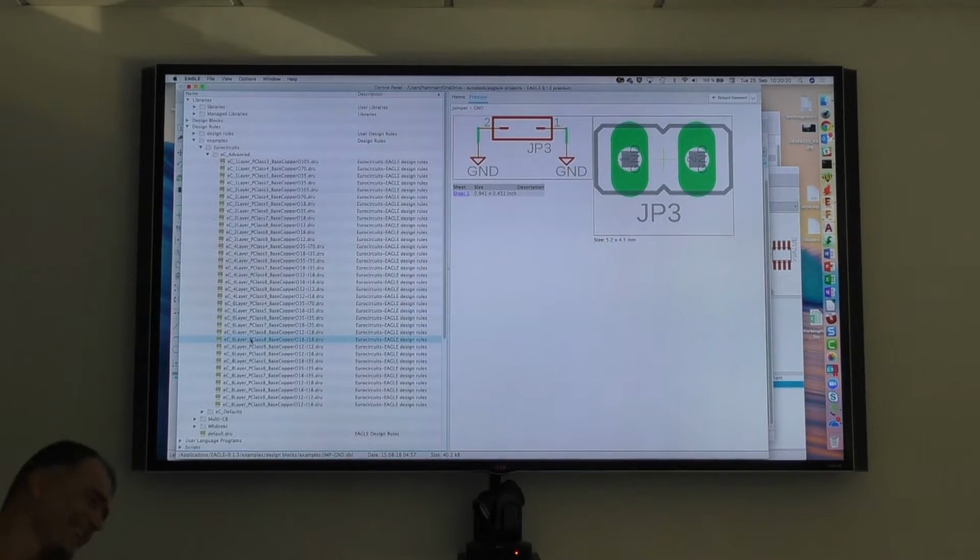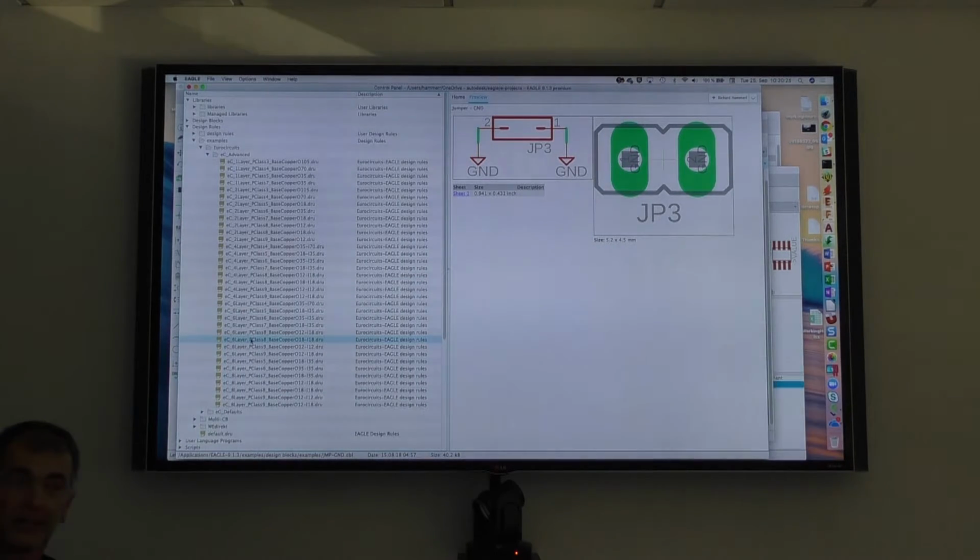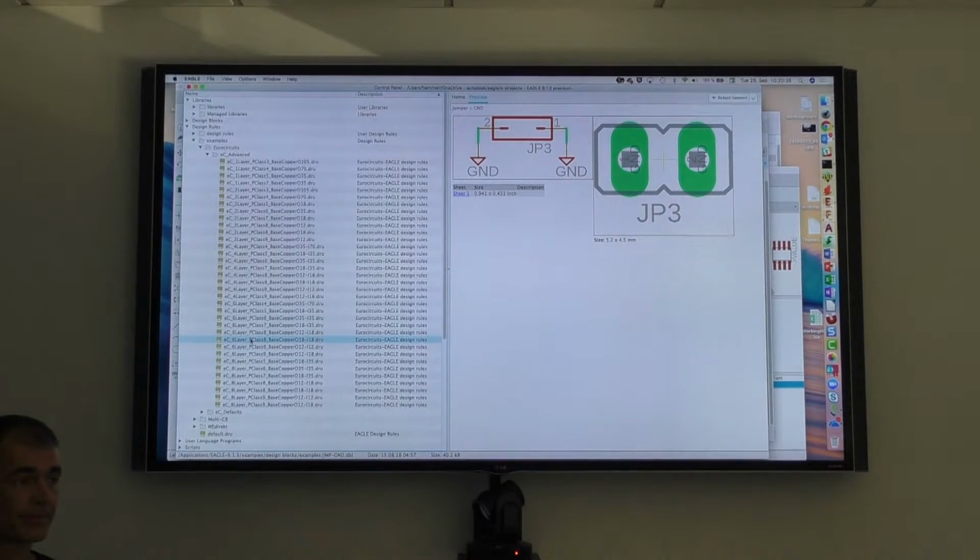Yeah, design rule errors. If you have some, and you send your board or the manufacturing data to the board manufacturer, they say, hey, we can't do it this way. There are two options: change your design or pay more money for it.